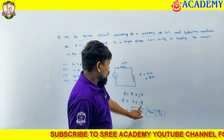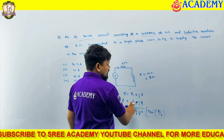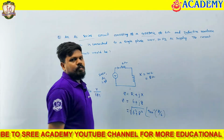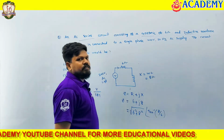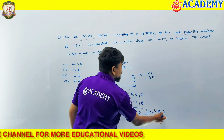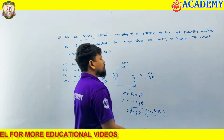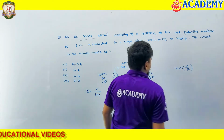J is there, that means that is the reactive part, and only 6 is there, it is only a real term, nothing but the real part, okay. So imaginary part divided by real part will give the angle for us, okay. So phi is equal to tan inverse of reactive part divided by active part, otherwise you can write it like this, tan inverse of reactance divided by resistance, okay.